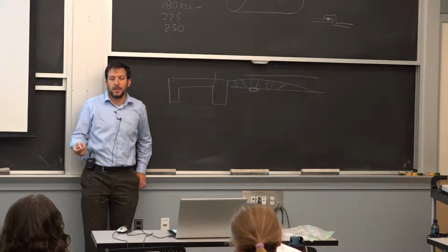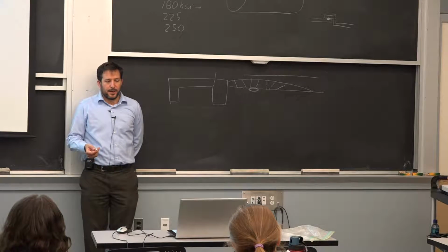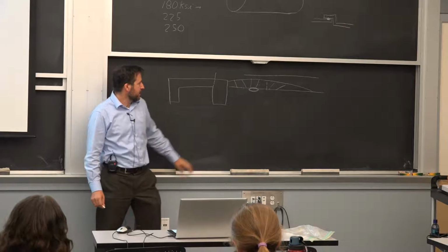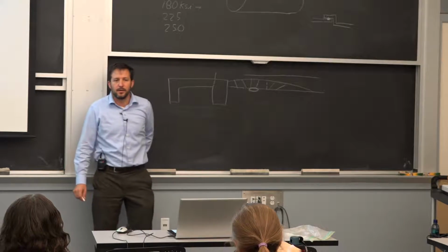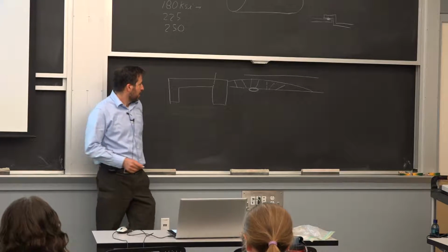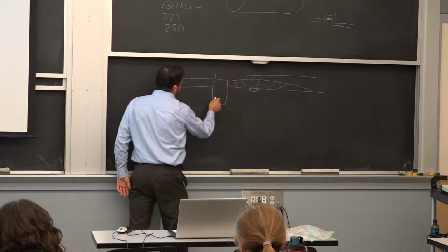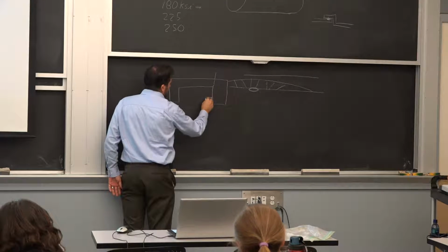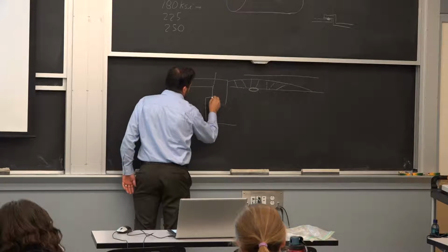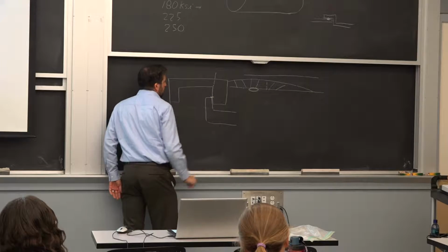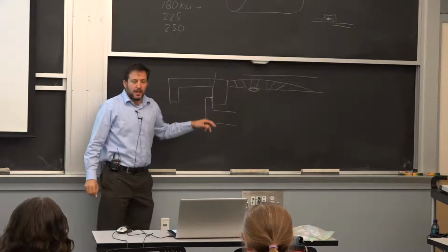Do I have something like a notch, a rolling defect? Do I have anything that can explain why the crack started here? And there wasn't any. In fact, what I saw here is the bearing mark against the pipe. So the pipe was only over here. It was showing here on the tab as opposed to all the way to the inside, very close to the joint.